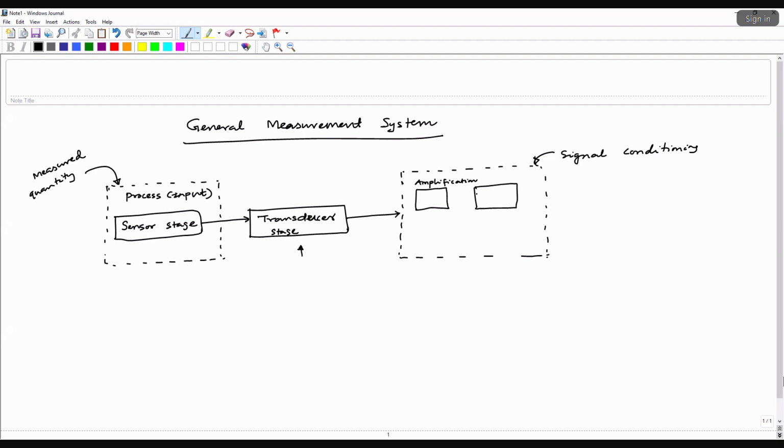Because of this, let's say the temperature is 50 degrees, it's not really reading a constant value, and it is varying between, let's say, 45 degrees to 55 degrees. Of course, there is going to be some inbuilt tolerance in the measurement, but when you have noise, it exceeds the tolerance limit, and you have to get a filter. You have to put an upper limit and lower limit to actually filter the noise. So you need to have a noise filter,